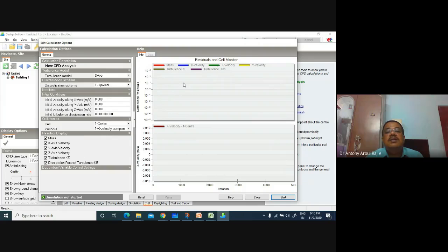When I solve all these things, I will be getting the residuals. We don't want a higher residual. So what is the residual? On the left hand side you will have the equation, and on the right hand side you will have 0. When you are using the guess and correct procedure, when you give the first value, the residual will be very high. As I march towards the correct solution, this residual value will decrease. Finally the residual should become 0, but there is no definition for 0. One can say 10 power minus 4 is 0, another can say 10 power minus 10, another 10 power minus 20, another 10 power minus 100. So you have to define the 0 for the computer. That is called the convergence criteria.